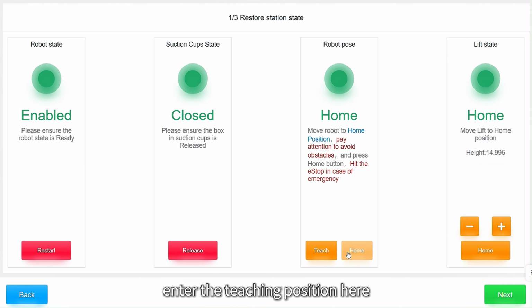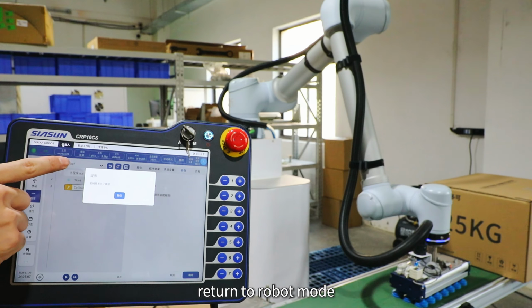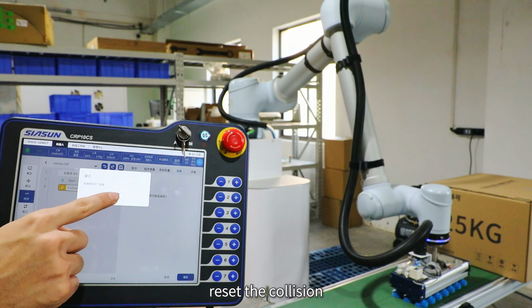Enter the teaching position here. Manually adjust the robot's current position through joint or end effector mode, making it enter a non-interfering area. Then click Hold to Home. Return to robot mode. Reset the collision.